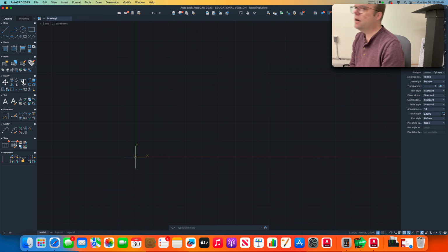I want it to end at 15,10, which means the other end of that line will be at the spot in the grid that is 15 on the x and 10 on the y, and you will have drawn a diagonal line. Okay? So that's how everything is drawn in AutoCAD.